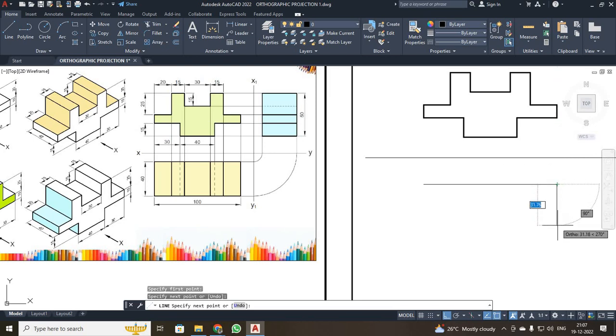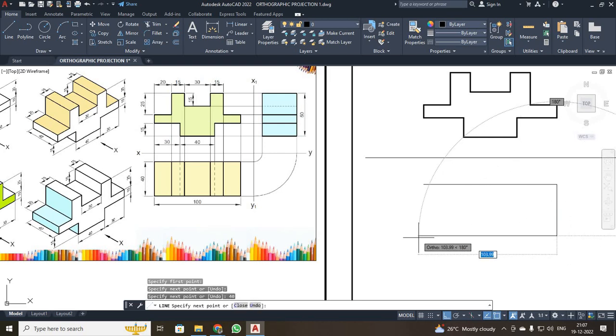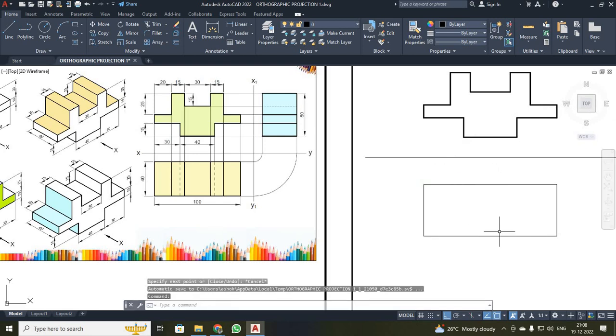So this is my first line. I know the height is 40, it is given over here, so I just moved your mouse, it is 40, enter. Once again I moved your mouse in the horizontal direction, placed the pointer over here and dropped it, so that I will be getting a construction line and I will be closing it. See students, there is no need to draw any construction line in AutoCAD software as we draw in the manual condition. We are going to just project it.